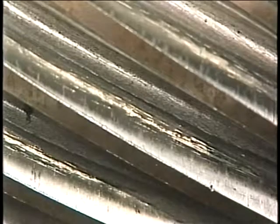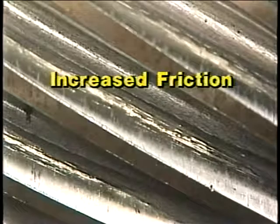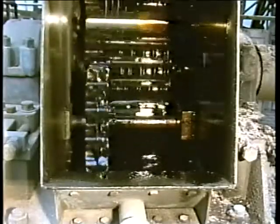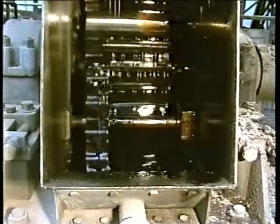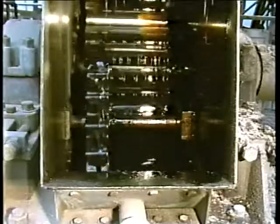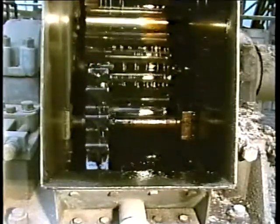The use of the wrong type of oil or grease for a gear set results in increased friction and rapid wear of the gears. Heat can cause problems for gears when a lubricant does not remove the heat quickly enough. Heat damage can cause gears and gearboxes to distort, which can result in severe misalignment and damage.